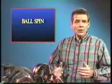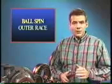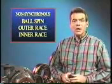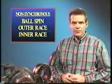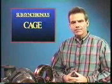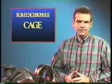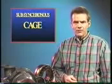energy. In our approximations, we've shown that the ball spin frequency, the outer race frequency, and the inner race frequency are all non-synchronous energy. The cage frequency is subsynchronous energy. That is, it rotates less than 1 time per shaft revolution. Therefore, a subsynchronous frequency is a lower frequency than shaft turning speed and is a fractional order value.